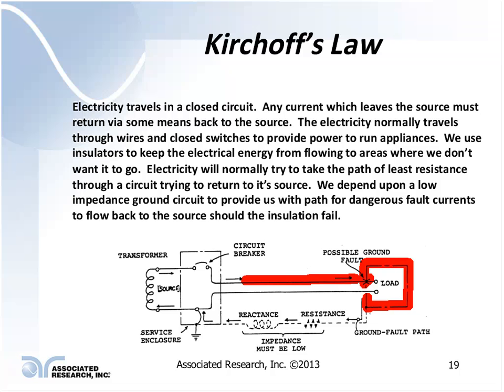This tool or product could continue to operate. So now anybody that, let's do a little stick man out here, if I'm standing here in contact with this and in contact with earth, that current is now going to flow through my body back to ground, and I'm going to be dead, because this ground circuit was defeated. Somebody cut off the ground pin of this tool.